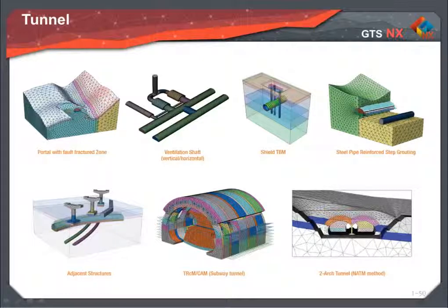The tunnel wizard can model tunnels having regular patterns and define excavation methods such as full face cut or bench cut. We can choose an excavation direction from one end or from both ends simultaneously. For each case, load relaxation can be considered by applying a load distribution factor.